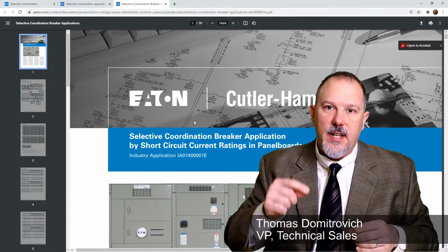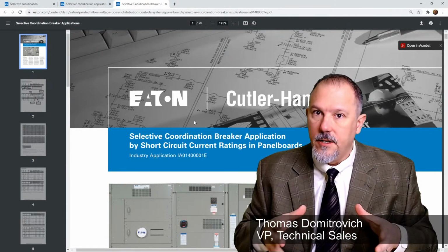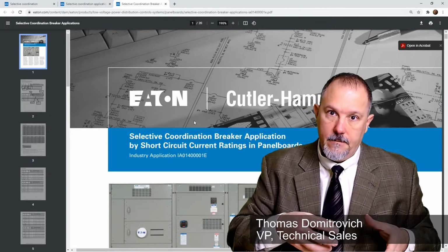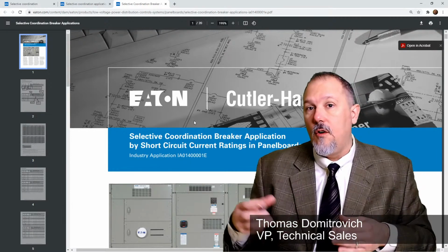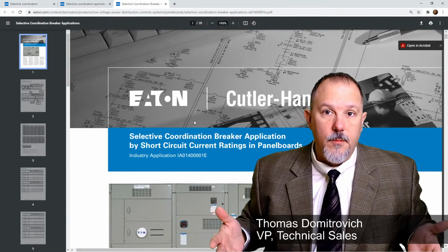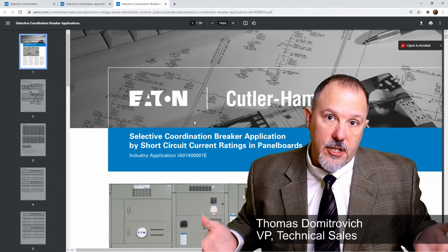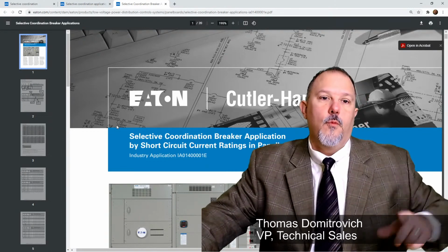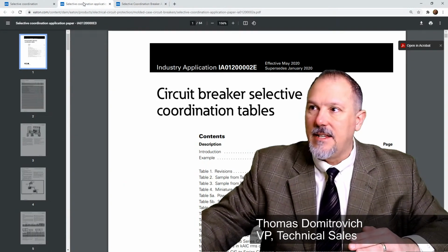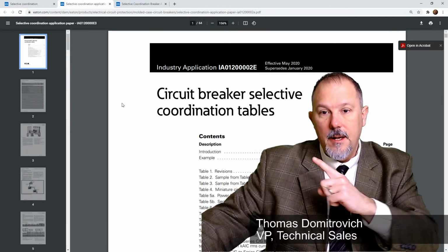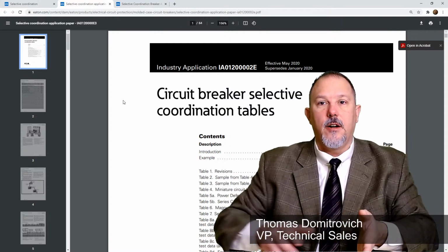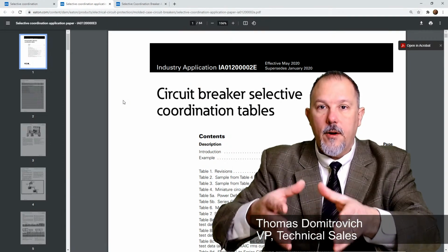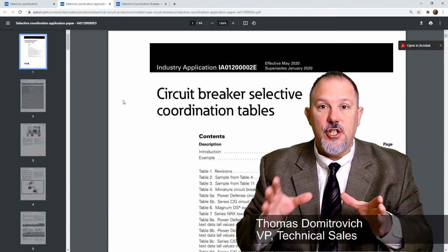One of the tips that I would say is make sure whatever circuit breaker or fuse that you pick, you understand what you can put it in. Because not all circuit breakers, not all fuses fit in every panel board, switchboard, motor control center, whatever it is that you're looking at, that any one manufacturer makes. So be mindful when you select your overcurrent protective devices, you may select it based upon this document, but you'll have to look at other documents and our consultant application guide and whatnot to see what device you picked, what equipment it fits in, and then what location does it fit in?